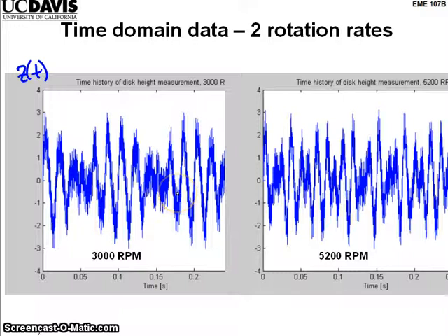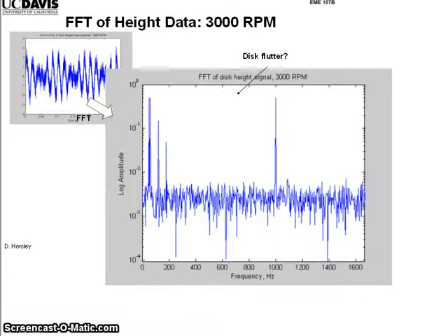If you look at these waveforms, you can see stuff that definitely looks periodic. It looks like a sine wave, but it's not at all obvious what information is in these waveforms. The time data doesn't really tell us very much; it's kind of mysterious. Now, in your MIDAC, this kind of data would be what you would record with the oscilloscope. But if you use the dynamic signal analyzer, you get a plot of the spectrum. I didn't have a MIDAC when I did this. Instead, I used what's called a fast Fourier transform, or the FFT, and that's the same thing the MIDAC's dynamic signal analyzer is doing. It's using an FFT.